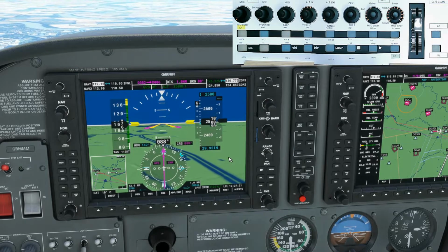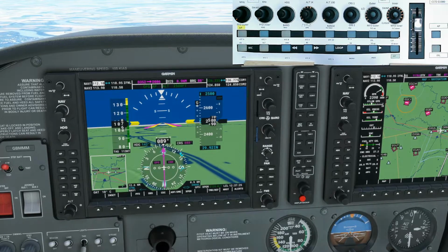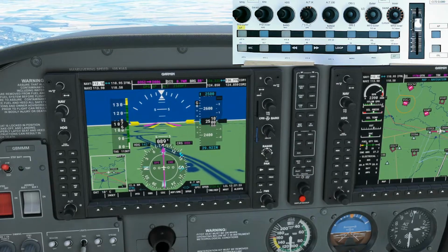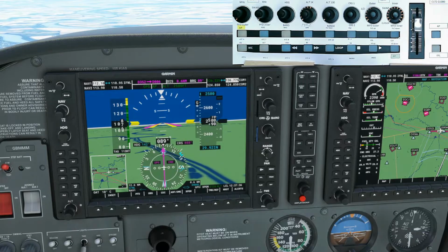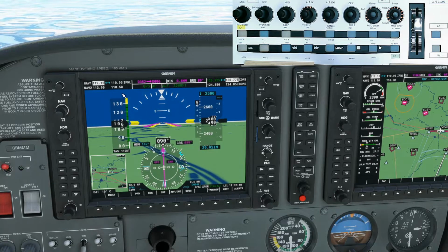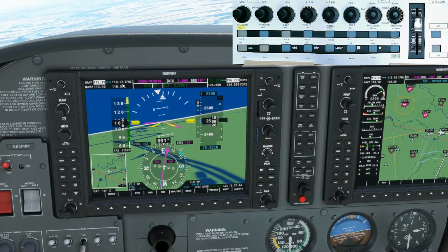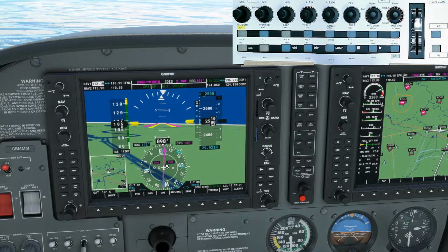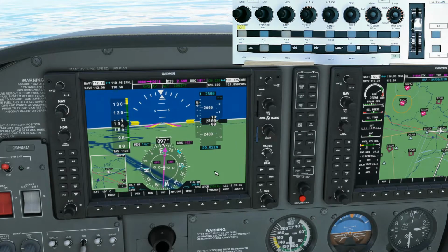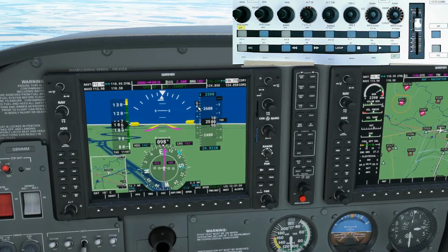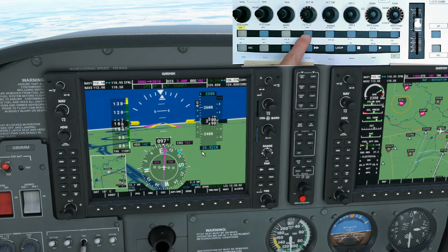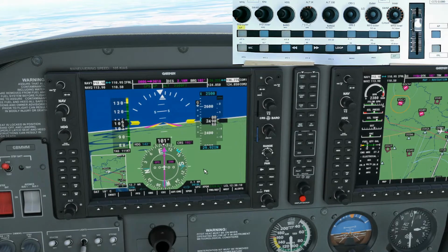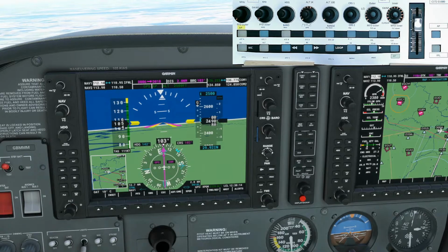Getting closer. Now, because you've got the localiser frequency already programmed in here, as we make our final turn in, when it picks up the localiser, this should change automatically from GPS mode into localiser mode. We shouldn't have to touch anything. But what it won't do is pick up the glide slope automatically. We actually have to change here into approach mode for that to happen. It will indicate it, but it will fly straight through the glide slope and won't pick it up and descend automatically unless we put it into approach mode. But you'll see that happen in a minute.